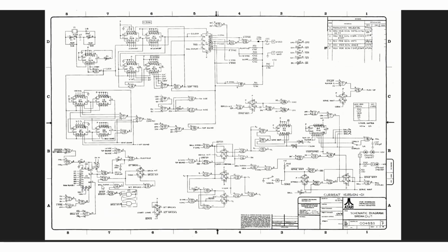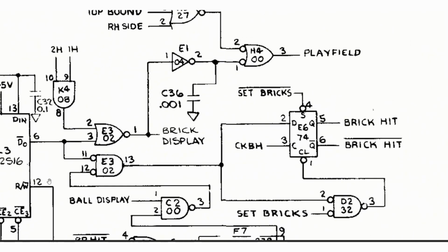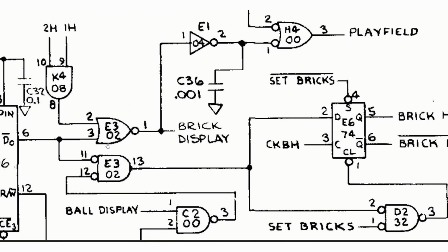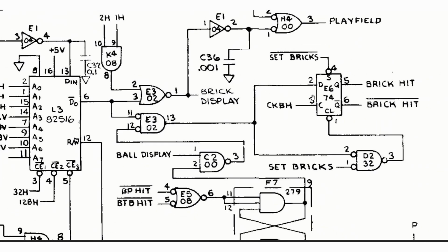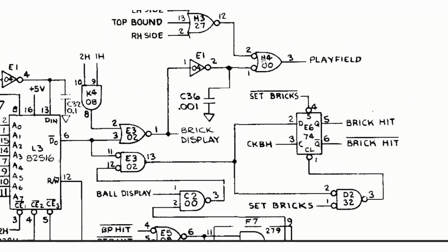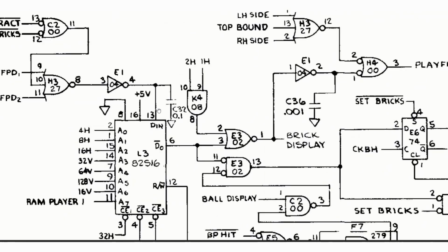Another really interesting thing is the use of De Morgan notation. For example, here we've got this NOR gate, the 7402, which is a quad NOR gate, and we've got another gate in the exact same package down here, but it's shown as a negative input AND. So these two are actually logically equivalent. And you'll see more of this around, like we've got this negative input OR gate here, and the 7400 is clearly a quad NAND gate. We see a 7432 gate here, which is a quad OR, and so this is a negative input NOR. You'll see a few of these things around here.